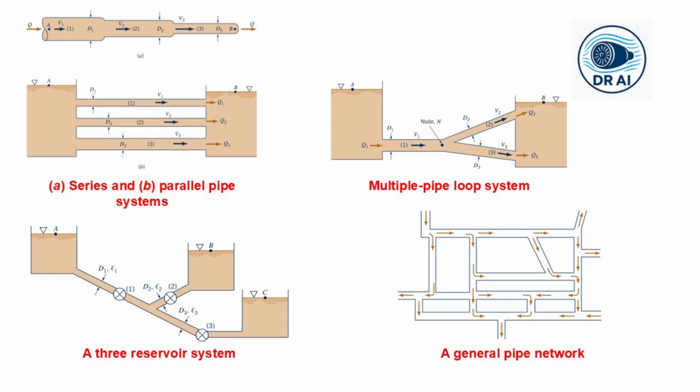So if you are given the flow rate, this is a Type 1 problem for each pipe, added together, a straightforward one. But if you are given the total head loss and need to find the flow rate, it becomes a more complex iteration because each pipe has its own friction factor that depends on the common flow rate Q value.